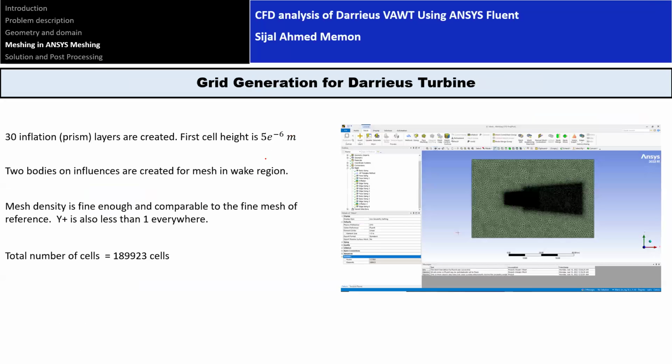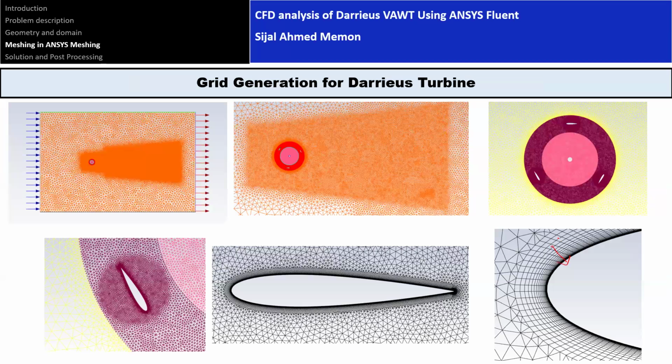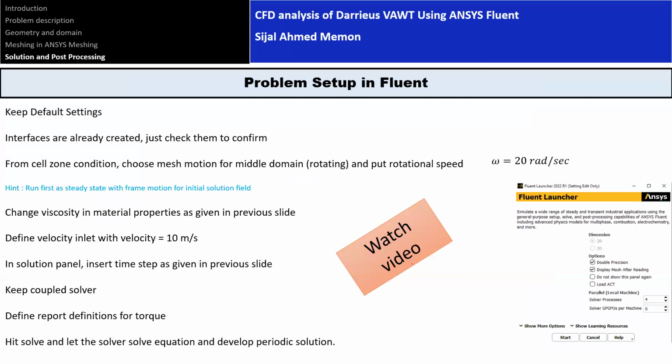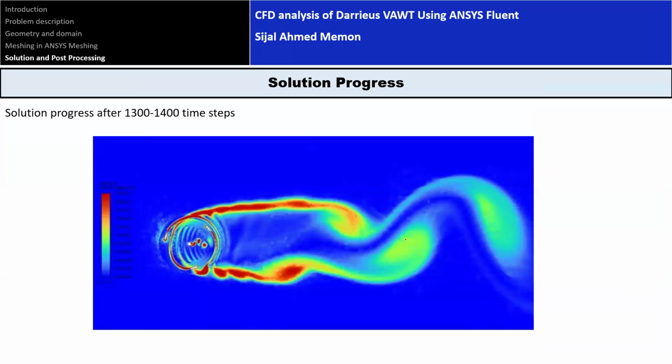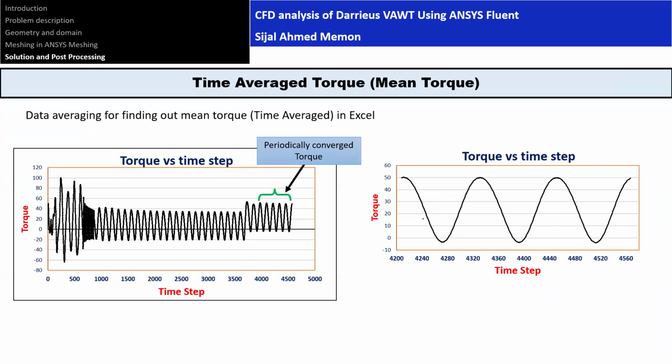And finally, you can see the mesh, which is created with the help of this domain scheme and the meshing scheme. And you can see also, we have very nice Hexa meshing in the close vicinity of the aerofoil, and away from it we have the tetra meshing. So this is the whole overall procedure for the solution. We will discuss them in detail in the course.